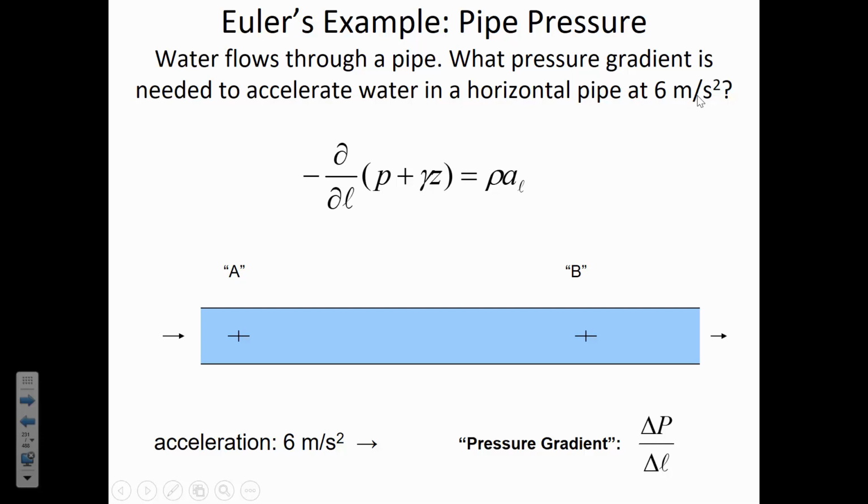So this is a little bit different from the previous time that you had acceleration in an enclosed nozzle. You know, we were talking about convective acceleration when there was a nozzle where the diameter was decreasing and that was causing the velocity to go up. Here, this is not an acceleration with respect to position like that previous example with convective acceleration was, but this is acceleration with respect to time.